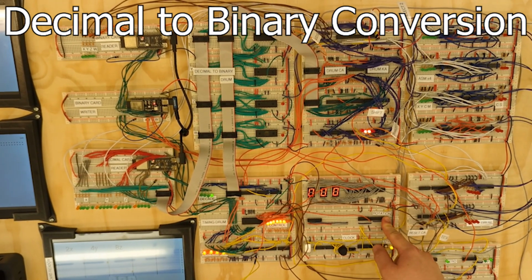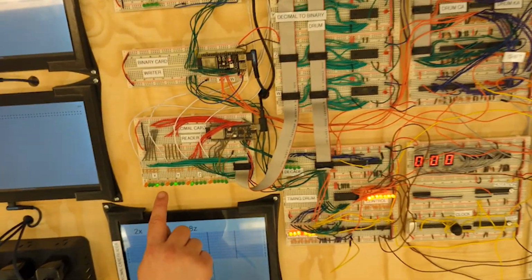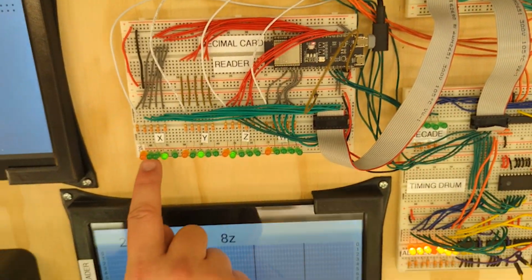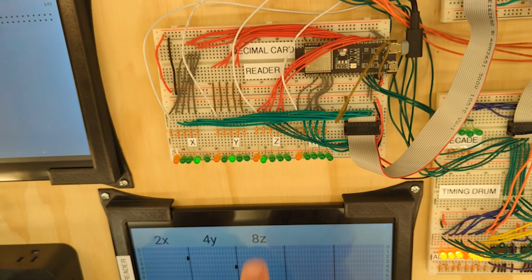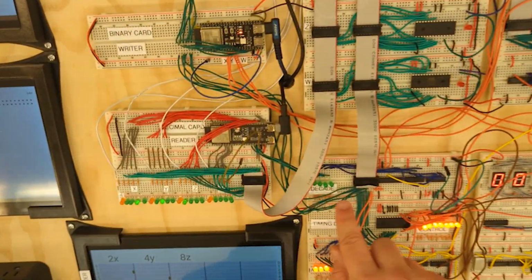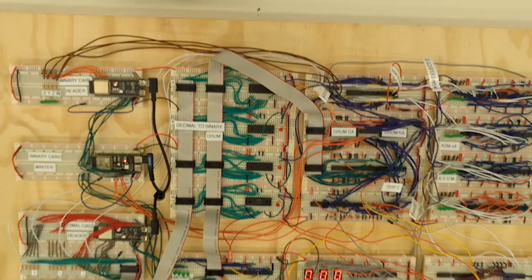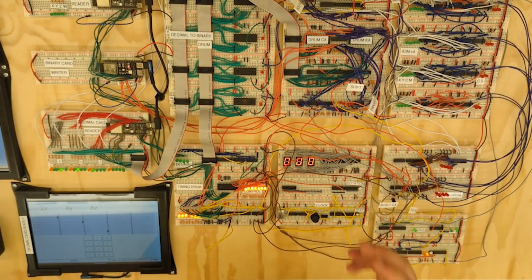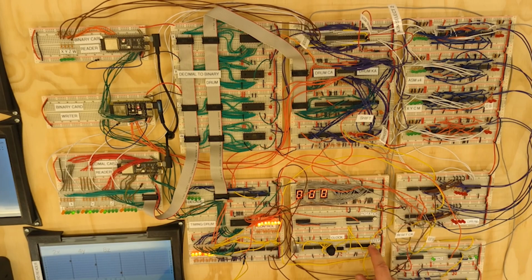We'll finish this cycle out. So now that our decade is 0, we have this bit asserted to represent a binary 2, this bit 4, and this bit for 8. So that is going to combine with our decade here and our timing address here to create the address for these EPROMs, so that we should see the 2, 4, and 8 loaded onto our drum.